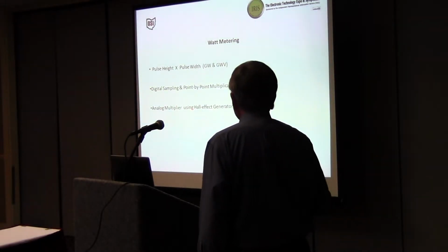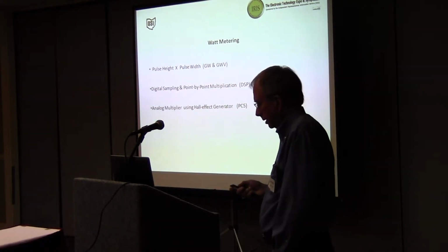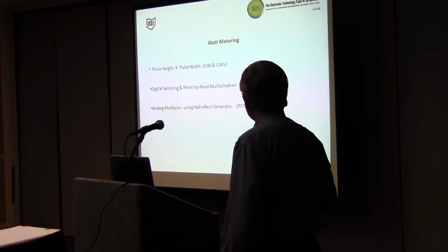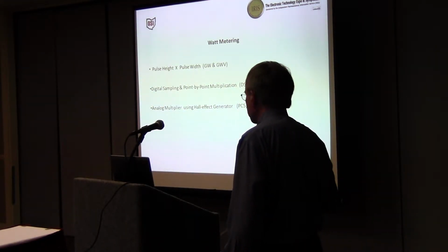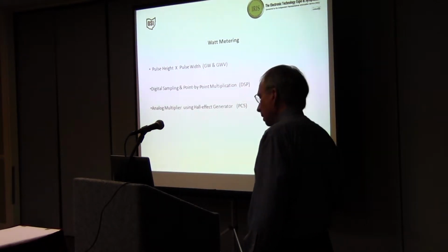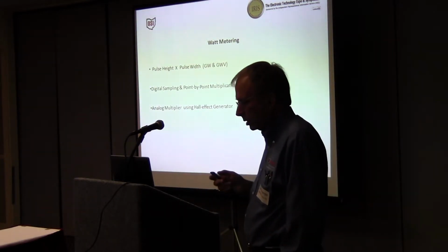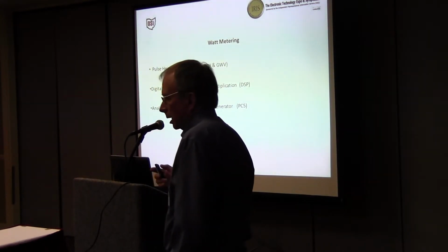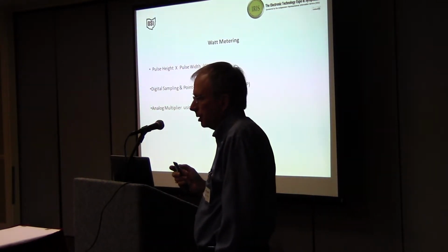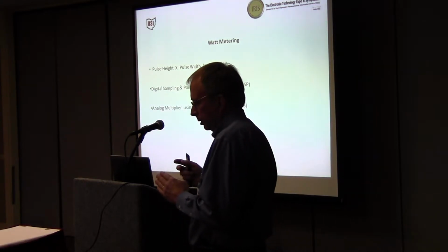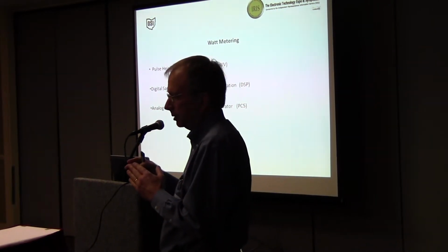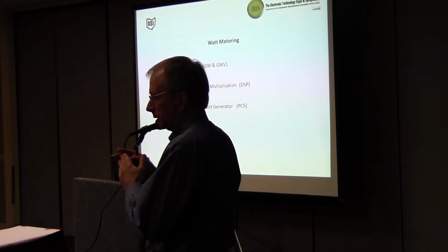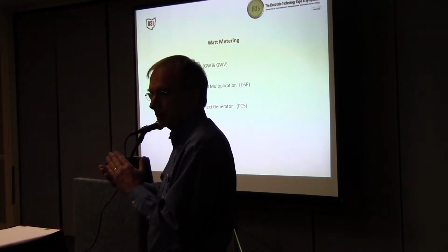And then there's another way of doing it, and I don't know whether people will understand this one or not, but this really goes back several years. There's a thing called a Hall generator that is a magnetic field sensor, and you put a current through the Hall generator, and you put the Hall generator in a magnetic field, and the output of the Hall generator is the product of the current through it times the magnetic field that it's in.